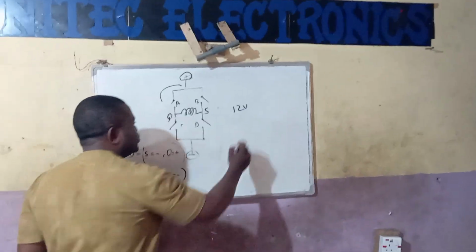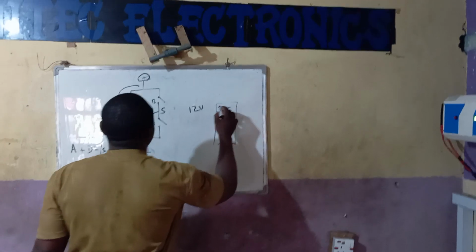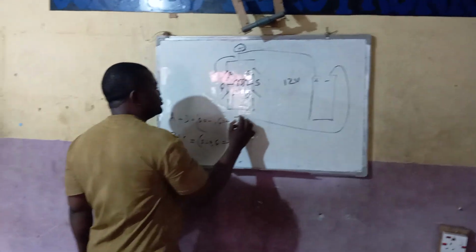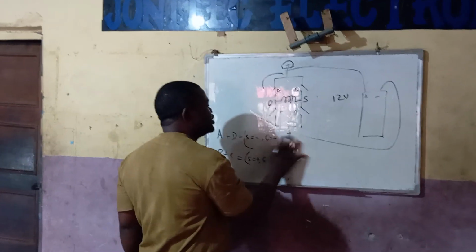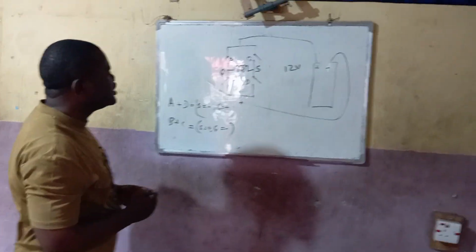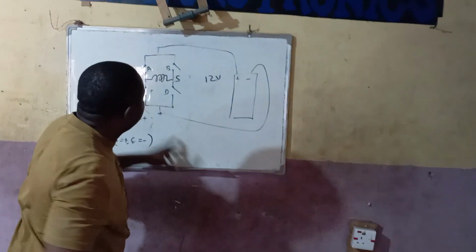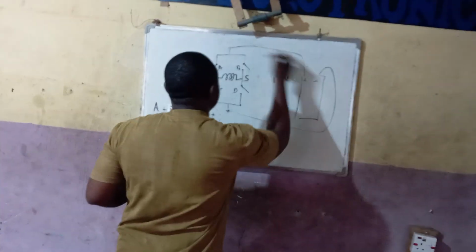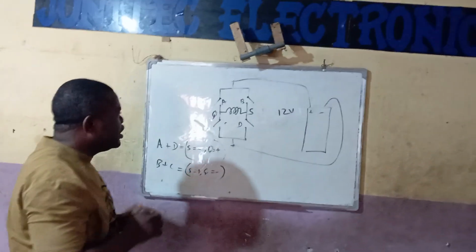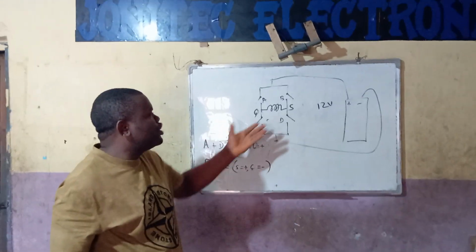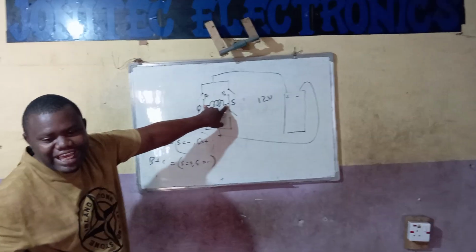So let's say one battery, plus and minus. We send the plus here, we send the minus here. Are we there? Yes. So let me clean these up. Clean this plus up and so on. So now the battery is the one powering it. This negative flows here, this positive flows here. So a 12 volts battery is what we are sending in. Once 12 volts comes in, it comes in as a DC. When it is going out, it is going out as an AC.